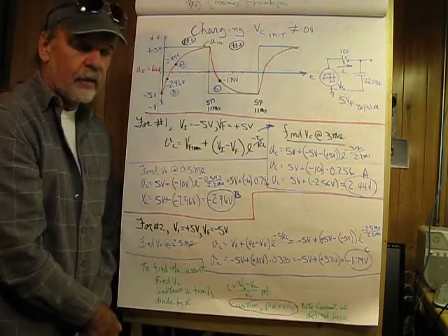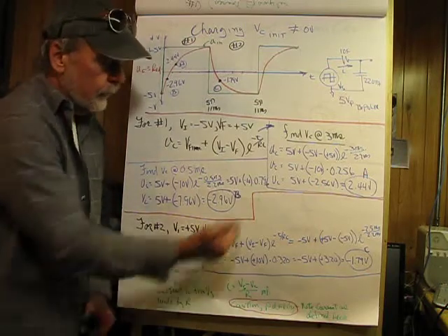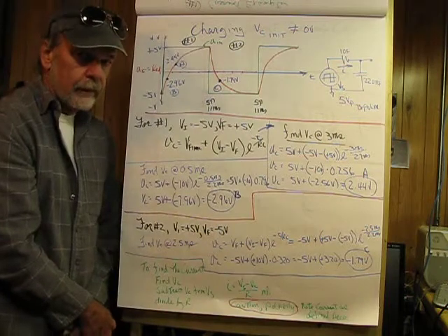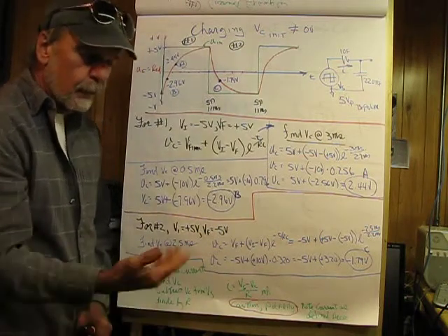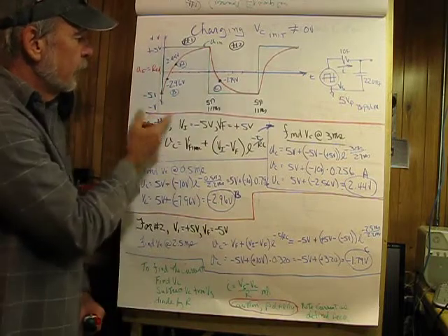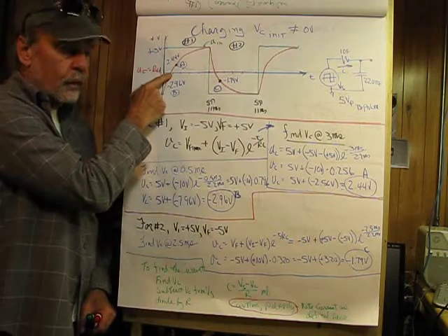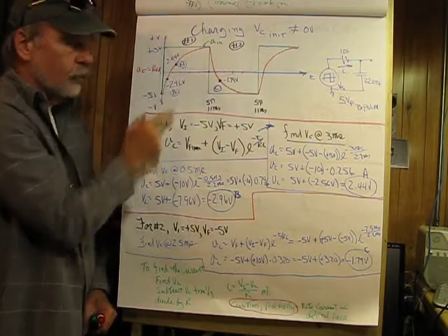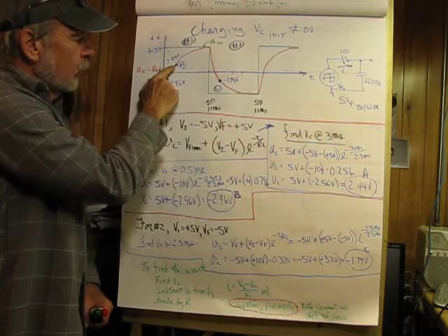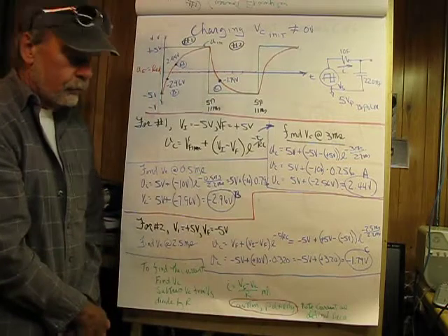Now, it's obvious that you need to keep careful track of your signs. So doing things like this here doesn't hurt. Anything that avoids a simple mistake is a good thing to do. If we look at that here, this would be 2.2 milliseconds, it's one time constant, two time constants, and so forth. So 3 milliseconds would be about here, and I call that point A, and that would be our 2.44 volts.